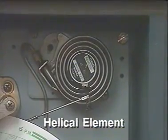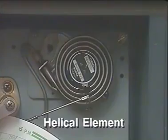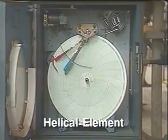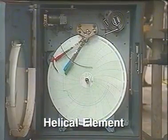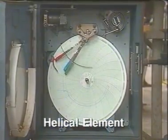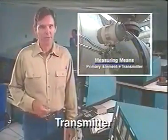This helical-shaped Bourdon tube, used in making pressure measurements, is connected to a process flow line by the metal tubing at the bottom of the element. Devices of this type are often called sensors or sensing elements because they change shape, size, or position whenever a process variable changes.